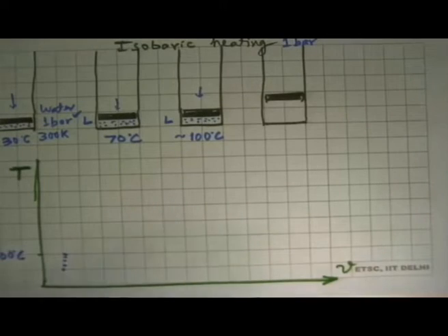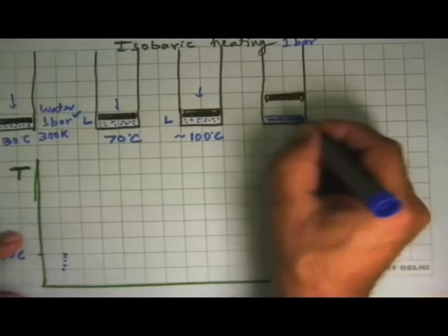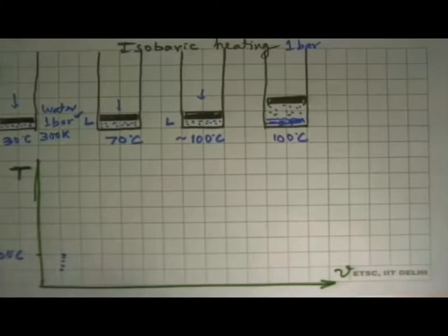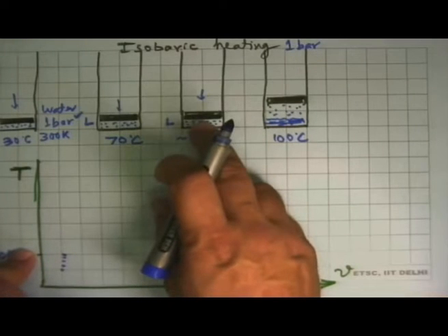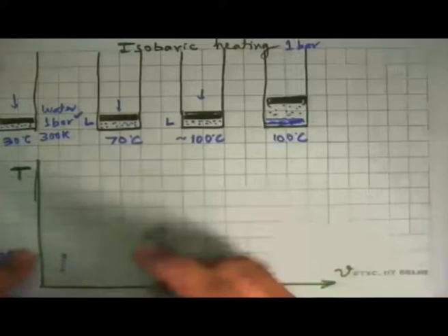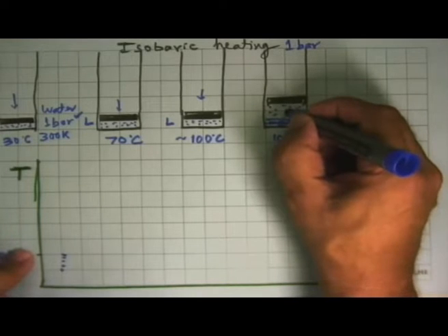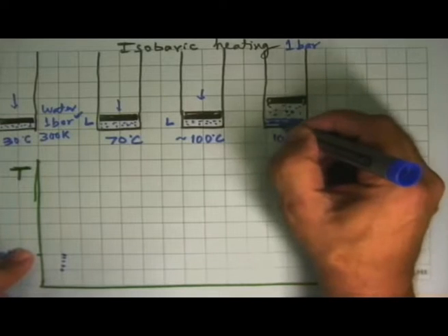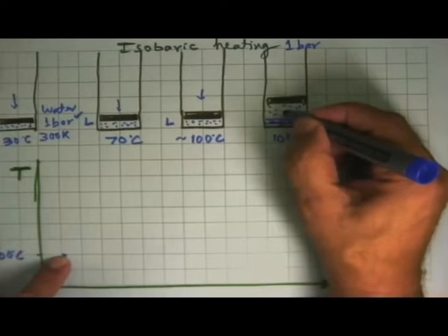And here what has happened now? This amount of liquid that was there, roughly that same liquid is there. And now here, what it meant, there was heat transfer to the system. It converted some of the liquid into vapor phase. Liquid is at 100 degrees Celsius, vapor is at 100 degrees Celsius, this is at 1 bar, this is at 1 bar, but the specific volume of the liquid is this small, the specific volume of this is much larger.